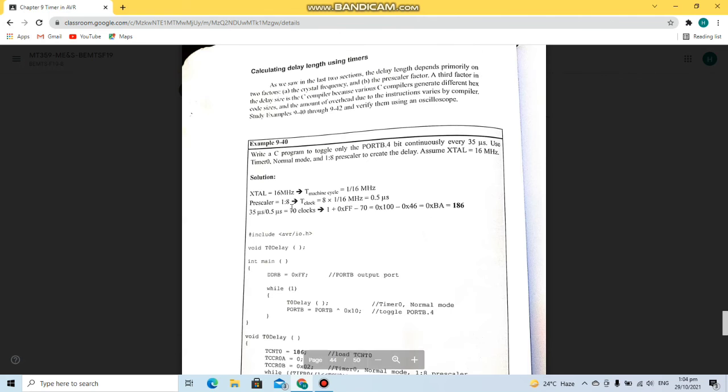And then coming to int main, we have set the port B direction to all pins output, and then we create a while loop in which we are first setting the output at port B to 0x55, and then we are causing this delay, which will go from 0x20 till 0xFF. 0x20 in decimal is the value 32. So from 32 till 255 we are going through these many cycles, wasting these cycles to create a delay, and then port B will change the output to 0xAA and then again a delay, and this will keep happening.